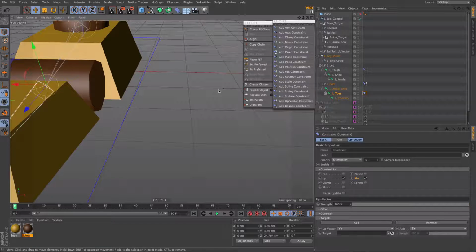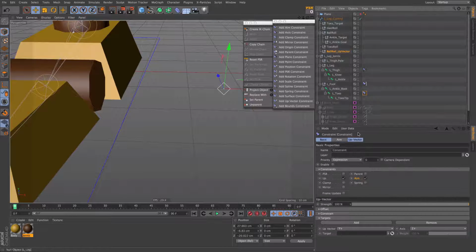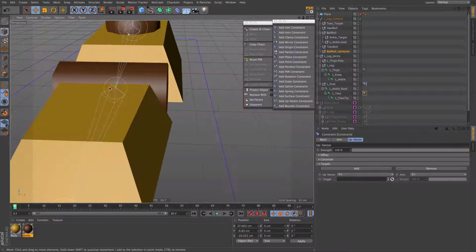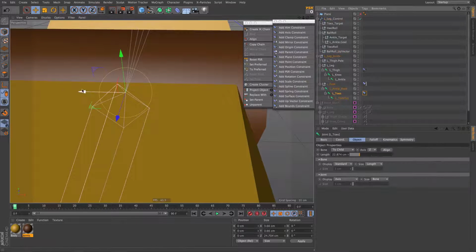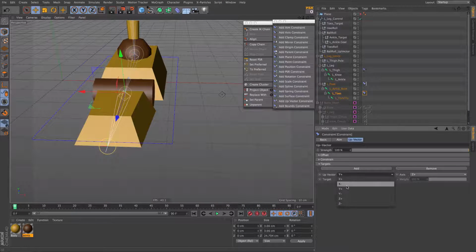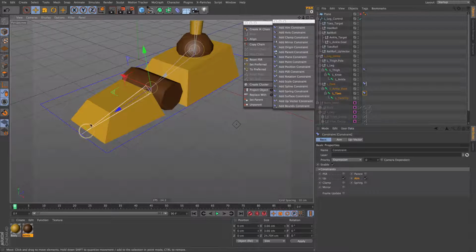So actually let's disable snapping and let's give a shape that we can recognize to this up vector, so we can see it visually. And we want this up vector to be on the z-axis that we used for aiming, and this time it will not be the y plus, this time it will be the minus x. So let's use minus x here and pick our up vector, and now if I enable it, it shouldn't move. So I enable it and it's not moving because it's using the exact values that we wanted.